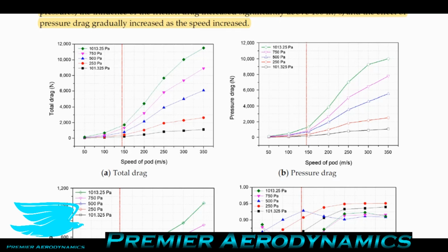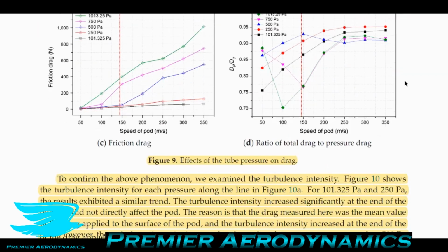Like even friction drag, when you have friction drag over an object, that's going to result in different pressures on the surface, and that's when you get a force on it. You can't have force without pressure on the surface. So all different components of drag will affect the pressure on the surface. But because we can decouple them better, we can understand what the different components are in terms of their magnitudes. So the pressure drag in total in this case is not just the wave drag, but also the traditional pressure drag idea. So I wanted to cover that there.